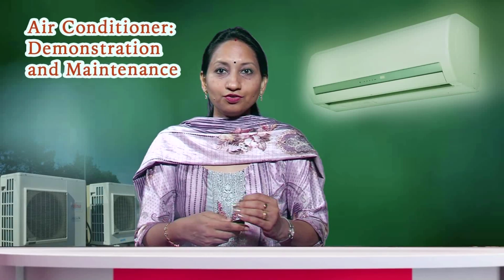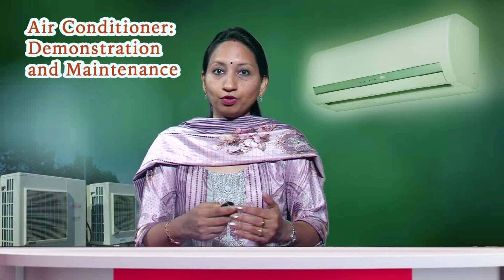Check the capacitor used by the blower motor. A faulty capacitor can cause motor starting problems and irregular operation. Also verify that the blower motor is producing adequate airflow through the AC ducts. That's all to check about the blower motor.